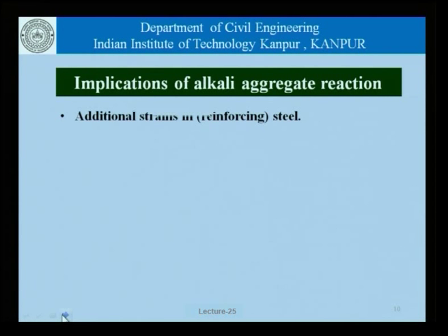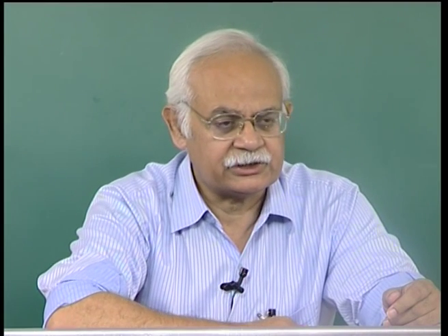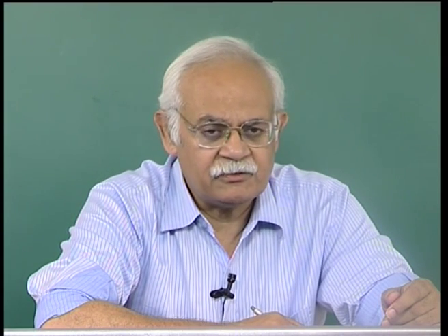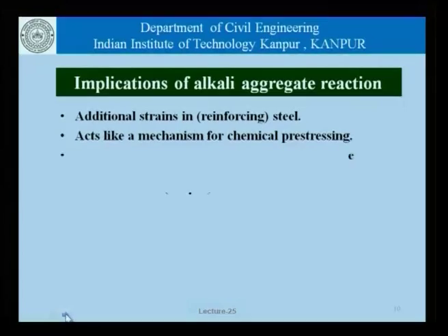As far as implications are concerned, we talked about additional strains in the reinforcing steel, and that is something which we will again talk about today. We will try to discuss that aspect in a little more detail, in the light that alkali aggregate reaction in reinforced concrete is something similar to inducing chemical pre-stresses in the concrete.